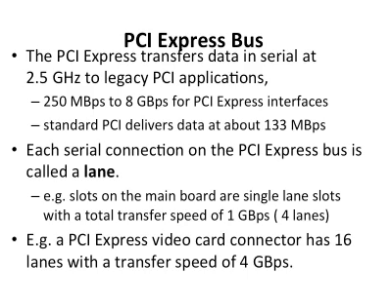After the PCI bus, people have been trying hard to improve the performance, as the PCI bus has its limitations on the bus speed. But at the same time, the advantage of the PCI bus is plug and play. With this configuration space, we can easily put different peripherals into a computer system, and they will work very nicely together, because the BIOS and the OS handle all the resource address allocation. We still want to keep that, but at the same time we would like to improve the performance.